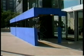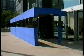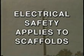If guardrails do not provide adequate protection from falling objects, then a canopy should be installed over walkways or work areas. The canopy must be strong enough to prevent falling objects from penetrating it and to prevent its collapse.